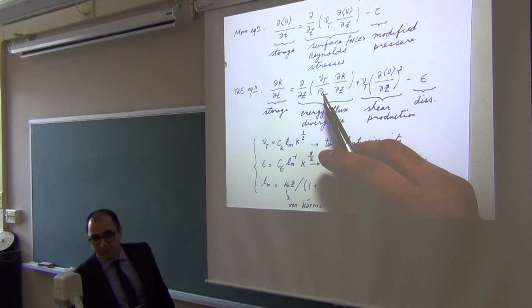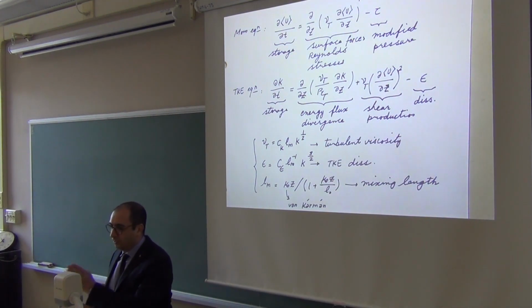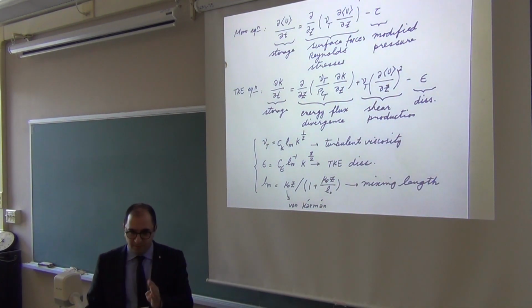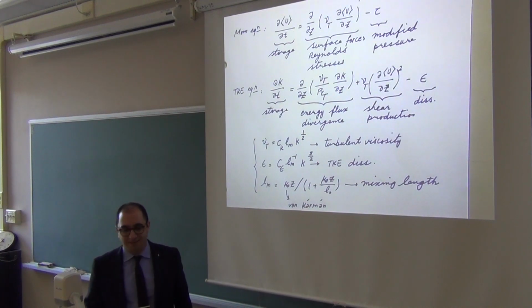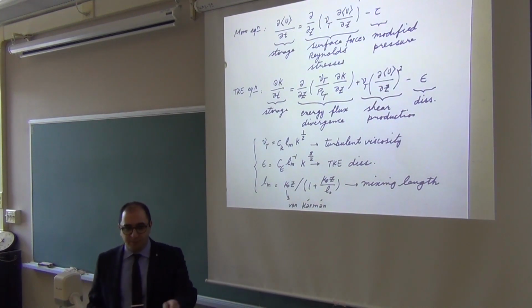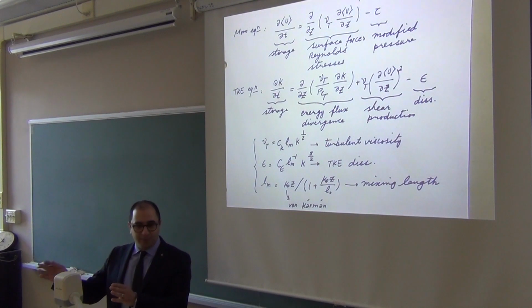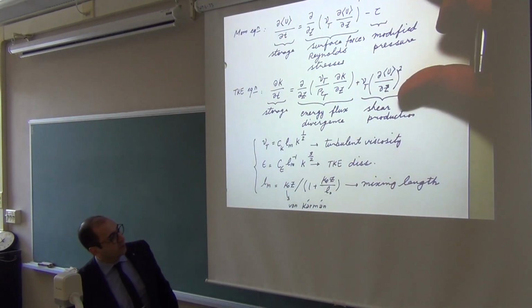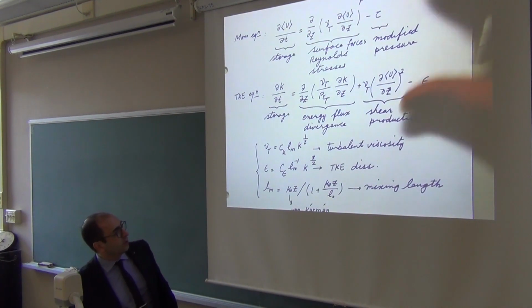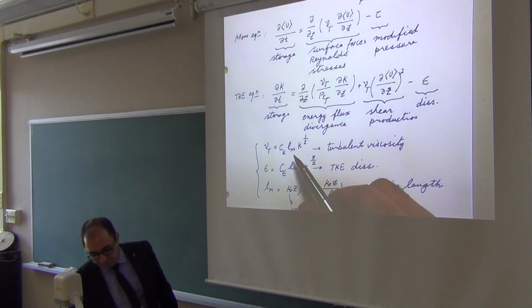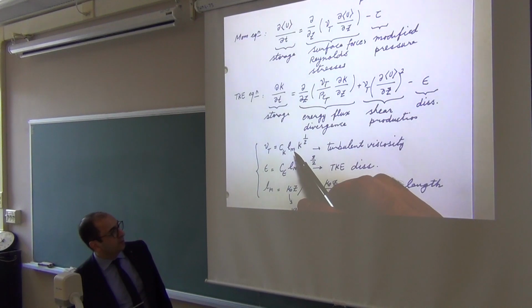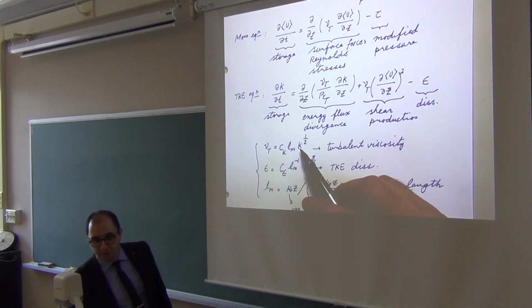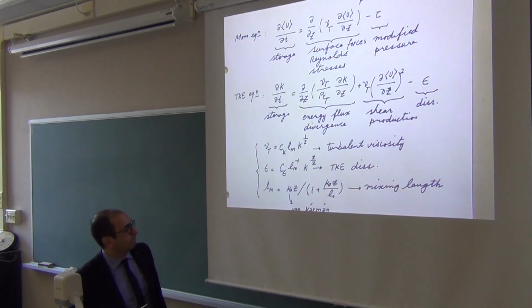In ordinary differential equations, you just have derivatives added or summed together, right? Different orders of derivatives, like second derivative, third derivative. You just add or subtract a bunch of them. That's an ordinary differential equation. But most turbulence models are highly nonlinear. There's also nonlinearity here, right? So you have one unknown, and you multiply by the square root of the other unknown. Very nonlinear. Everything else. So numerically, it's a headache to handle this.